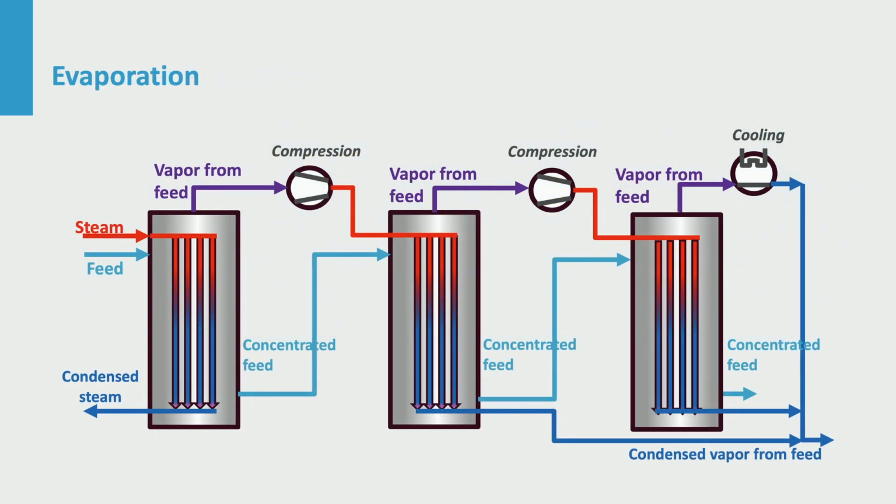Water evaporation is a major DSP operation. Also, a major DSP cost source because of the energy required. To minimize energy use, an option is shown in which the feed that needs to be concentrated enters the first of three so-called effects. The contents of the first effect are kept at the boiling temperature by using indirect contact with steam from an external source via a heat exchanger.